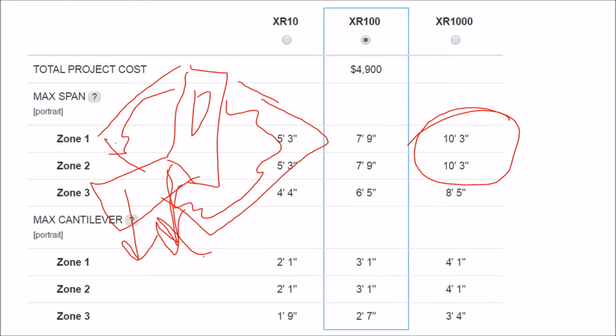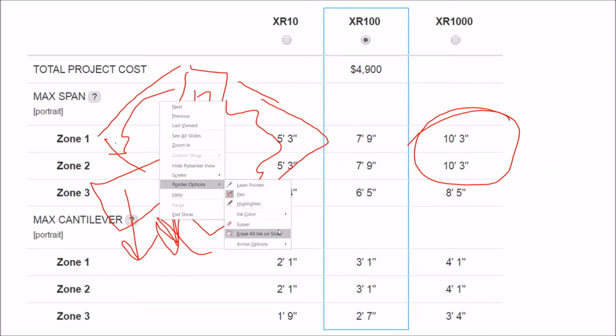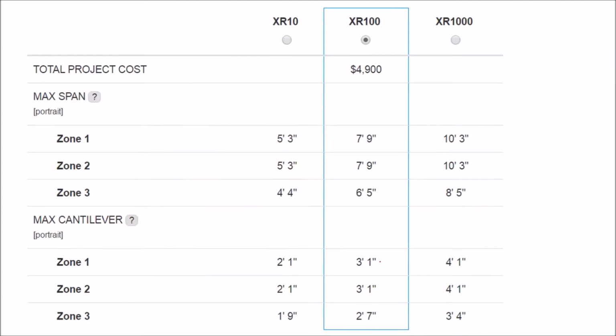So it's usually not the brand new solar attachment that leaks, it's the pre-existing holes on the rooftop that are not part of the solar array that get weakened during the install, and generally they're the ones that start to leak.